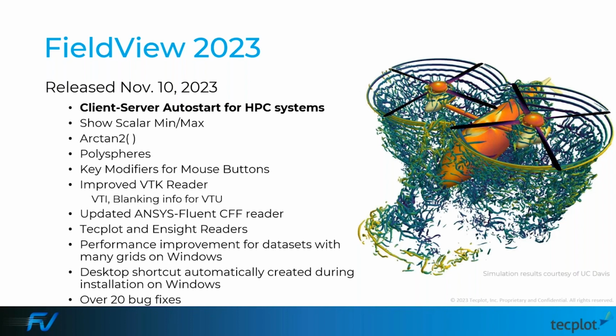I'm not sure if by copy paste the meaning is to copy paste in the same data set, or if that's moving them to another data set. Of course, that's already doable by saving a streamlines restart and applying it to the other data sets if you want to really match streamlines from case to case for comparison. But maybe the request is more for taking a group of streamlines and repositioning them. Yes. That's not readily available, but that's a good feature request.